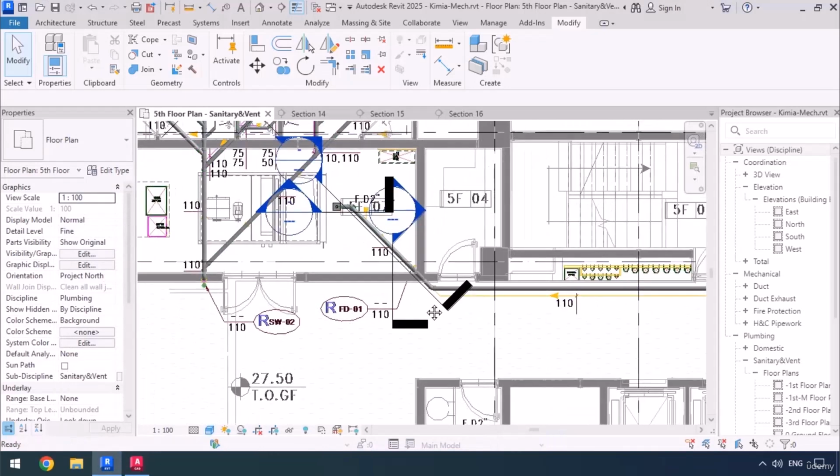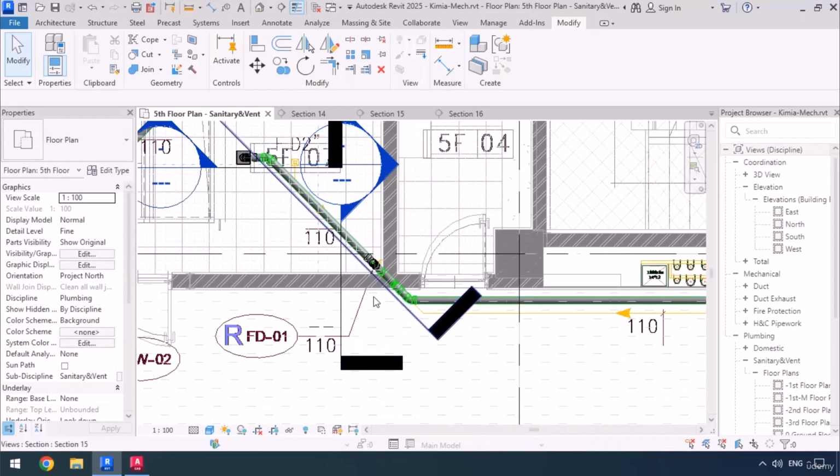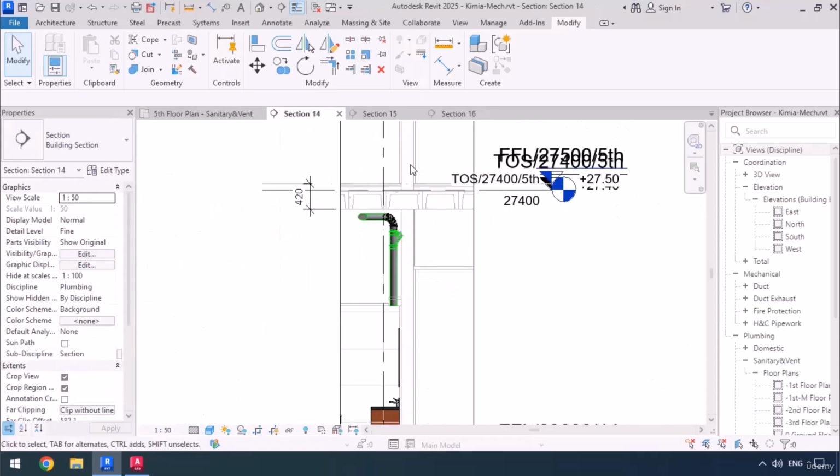Now let's go double check in the floor plans to see if the same thing has been demonstrated as in the riser diagram. In other words, we want to make sure there aren't any architectural flaws, and to make sure that the pipe doesn't interfere with the wall or anything else along its way.